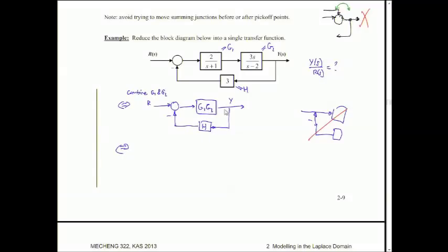So now we can combine the whole thing into one transfer function using the rule. I'm looking for Y(s) over R(s), the output on the right-hand side to the input on the left-hand side. In the formula, it's given as G over 1 plus GH. I'm putting it in quotes because I might be using different variables, but that's what I remember as the formula, where G is the forward path transfer function, which in this case is G1 G2, and H is the feedback transfer function, which is H still, so it's 1 plus G1 G2 H.